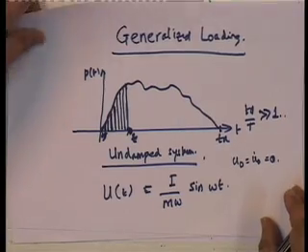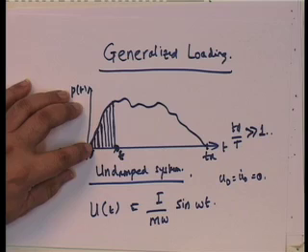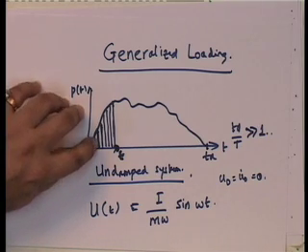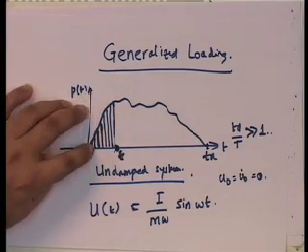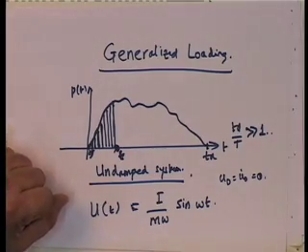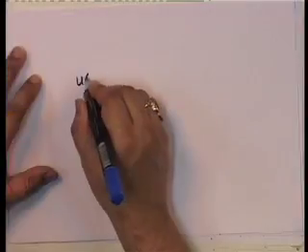Then all I have is an impulse at an instant. And note that the system is linear, so I can assume that each of these trains over here is a separate load, and I could find out the response to each load, and then I could superpose the loading.